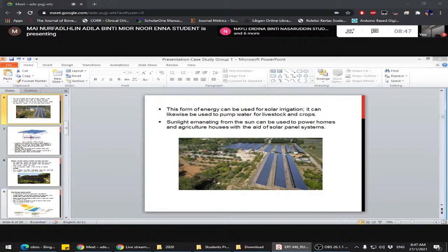How does the solar energy work? PV cell convert sunlight into DC electricity. Charge controller works to control the power from solar panel, preventing reverse flow back to solar panel which would cause panel damage. Battery system act as storage of electric power, used when sunlight not available, for example during night. The system is connected to inverter to convert DC into AC current.